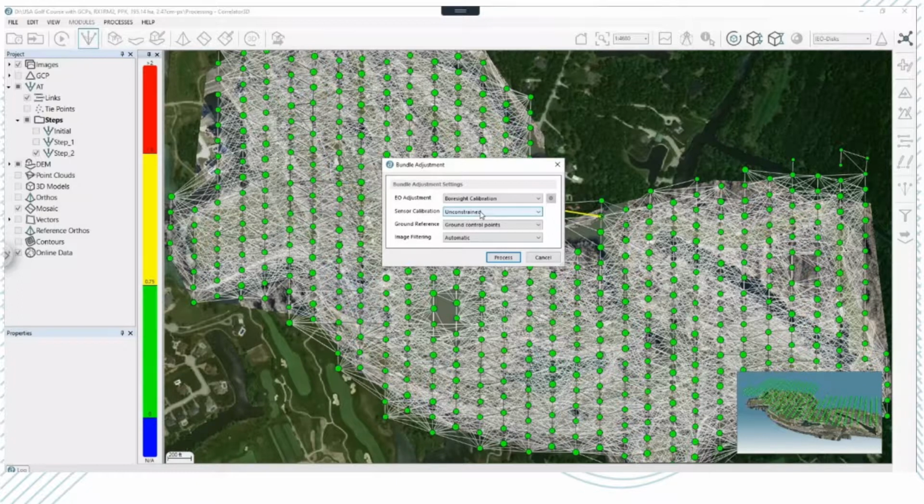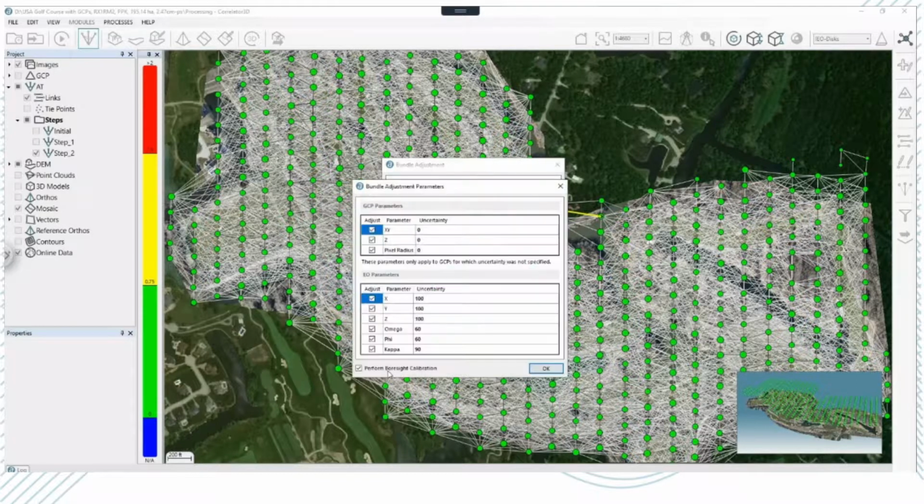And on the large format side, they do that as well. They set up a calibration field. They may fly it before a big project. They've got a very well-defined distribution of control points, so they can validate what they already have. And that's where boresight calibration would come in. Otherwise, you don't need it. I just wanted to bring that up because a lot of people ask, "Do I check boresight calibration?" Not necessarily, especially on the constraint option.